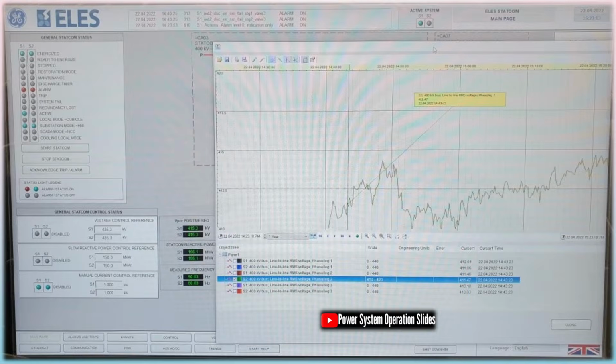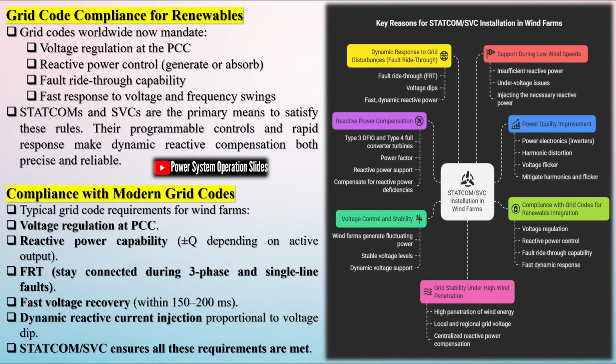To interface with the grid, the STATCOM uses a coupling transformer that matches voltage levels and facilitates the exchange of reactive power. A dedicated controller continuously monitors the grid voltage and dynamically adjusts the output of the VSC to either inject or absorb reactive power, depending on system needs. When the STATCOM's output voltage exceeds the grid voltage, it supplies reactive power to the grid, functioning like a capacitor.